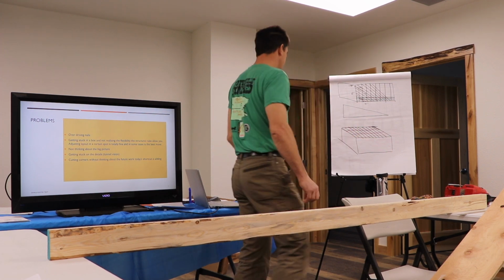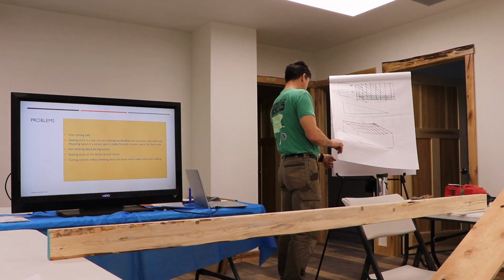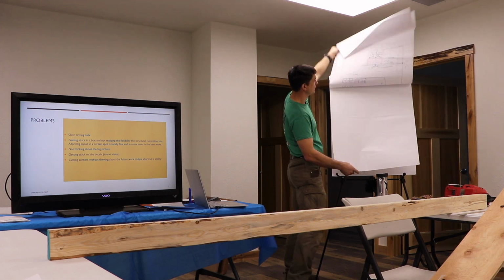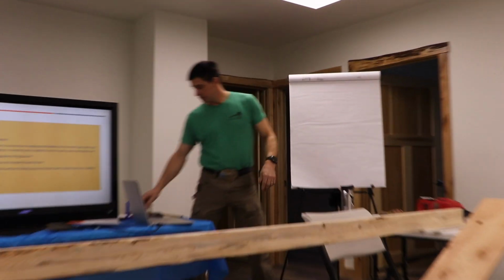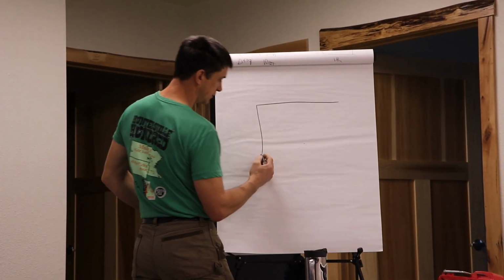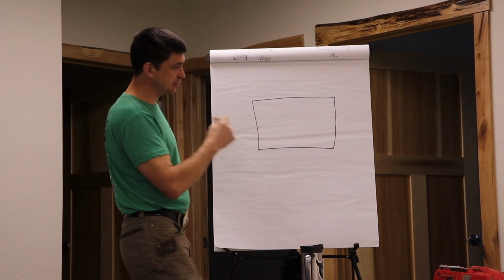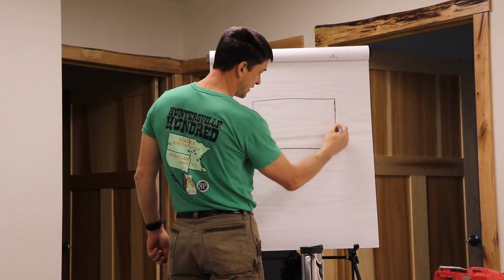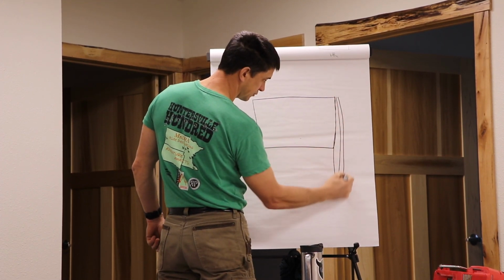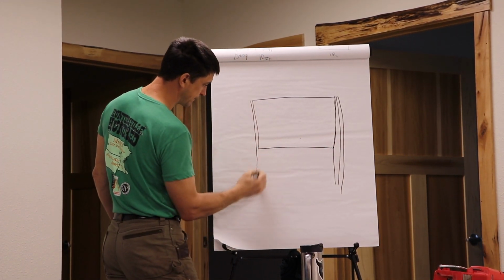you run into something like this. Okay, so we got a 7-foot wide window in this wall. Because it's over 6 feet, the building code says this opening has to have not 1, but 2 shoulder studs, because it has to have 3 inches of bearing for this header.